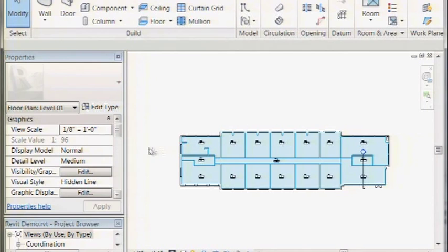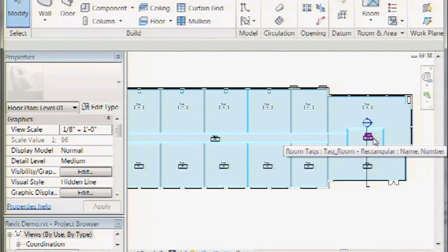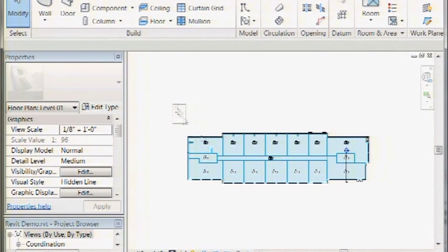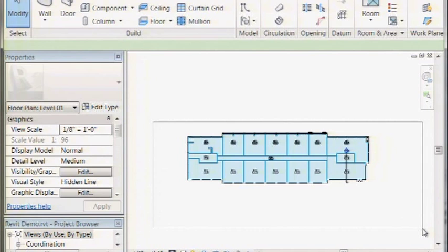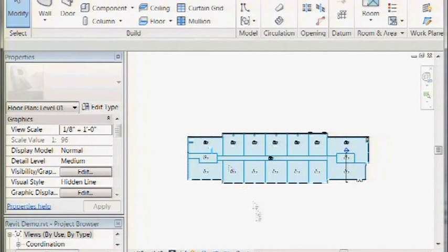You'll also notice that in this drawing, I don't have much in here. I don't have furniture, I don't have stairs, because you don't need that. What I would do if I got this model, let's say one of you sent it in, and I'm sure I've seen at least 1 or 2 of your models that have come in, I'm going to highlight this whole thing, and I can't see it right now because it's very small. Well, the resolution's off. But I highlight the whole thing, and I'm going to go to filter, and I'm going to get rid of everything that I don't want on this model. I can often reduce the file size of this model by 50%. So if you're sending me a 100 megabyte file, I can get it down to 50, usually.